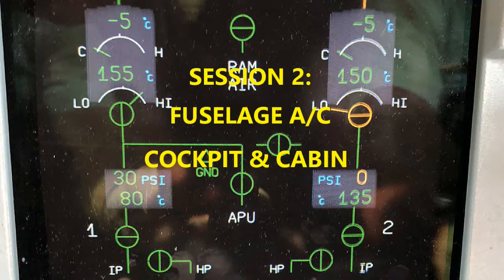So let's talk about the primary heat exchanger. The primary heat exchanger is located between the plenum and the main heat exchanger in the ram air system. This is where the ram air flows through the heat exchangers, which of course are cooling that air. You have main heat exchangers, so just so we're clear, there's a difference between your primary and your main. Your main heat exchangers are located upstream of the primary heat exchangers, and the main heat exchanger's job is to cool the hot air coming from the compressors of the air cycle machines.